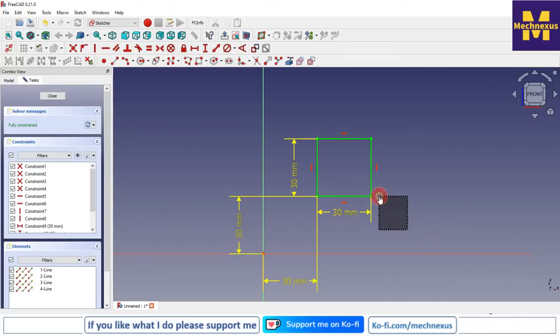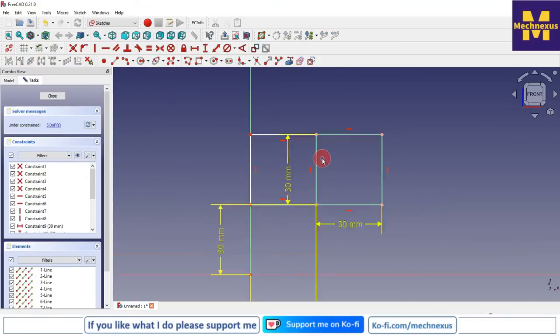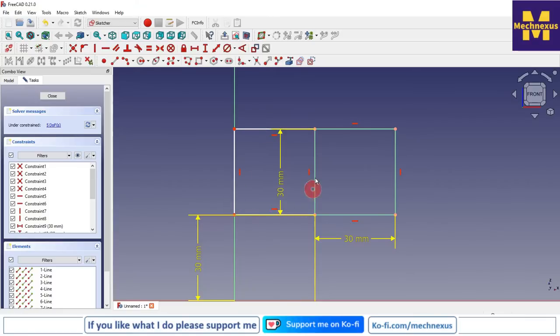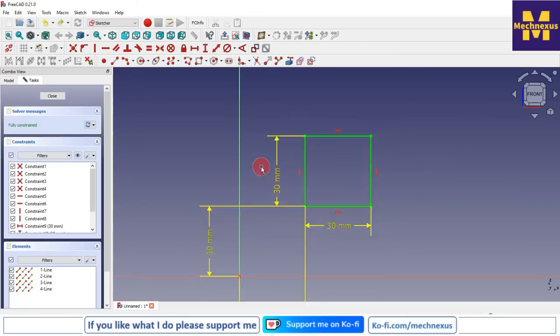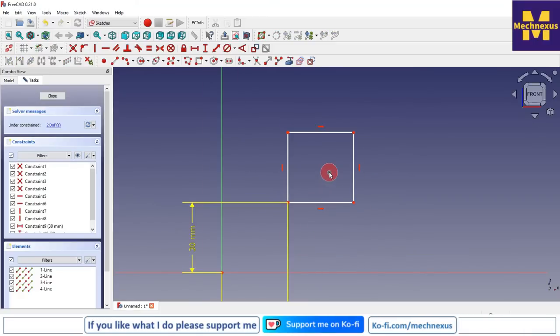Now I will select all this and click on symmetric. You can see that it got symmetric with our last selected edge. So here the edge is important. If I select this edge and this edge, and for better visibility I hide the dimensions so that you can clearly see my selections.